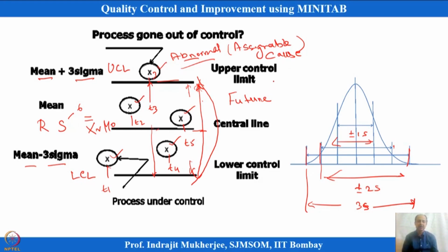It is not easy to identify, because if you have gone to the process, you have to immediately identify and isolate, then take action and then allow the process to run. This is not easy, because in a mass manufacturing environment you cannot immediately take certain actions. But you have to ask the operator, whenever something goes wrong, to please write down the causes, which are the abnormal conditions. Later on, offline, when the process is not running, we will take corrective actions on how to stop this, brainstorm and figure out, and then based on that take some precautionary actions, and monitor again to see whether these types of abnormalities occur again, for the specific root cause which was identified by brainstorming.